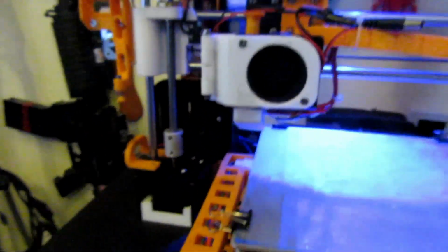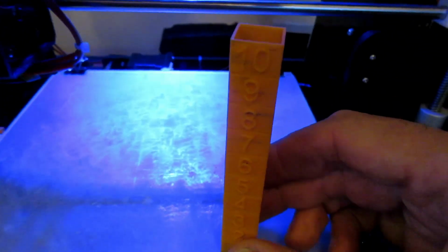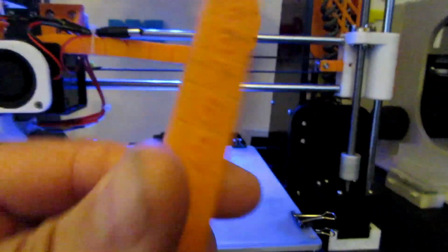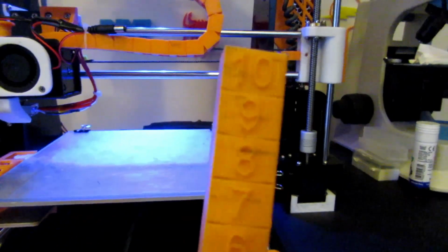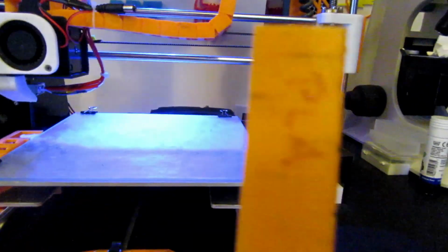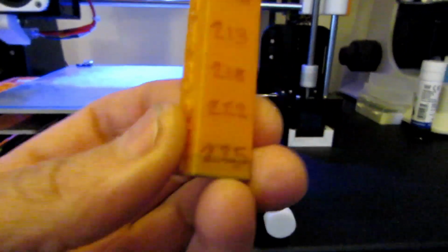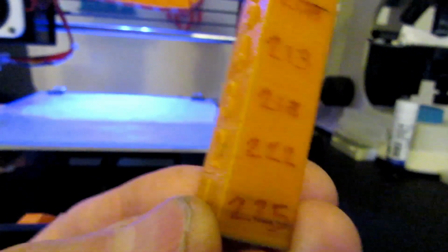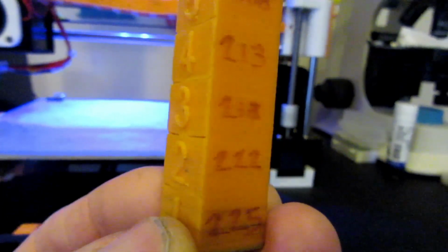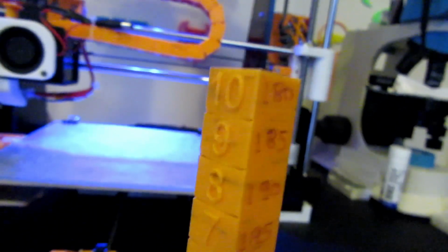So I know that it's going to be somewhere in there, which is going to be a good setting. So what you can do is, I mean, all filaments are different. What I've done is printed myself out one of these towers. And you can see it's 1 to 10. And if I turn it around, I've got it in PLA there that I've written on. And I've got some temperatures on the sides. So the first part up to number 1 was printed at 225. And then as I got to the last layer, I changed it to that. Change it down, change it down, change it down. So by the time I got to number 10, I was doing it at that 180.